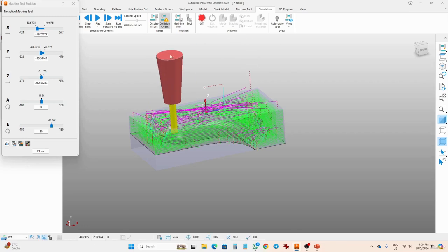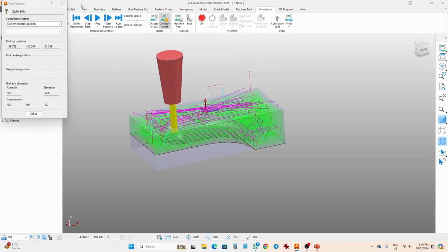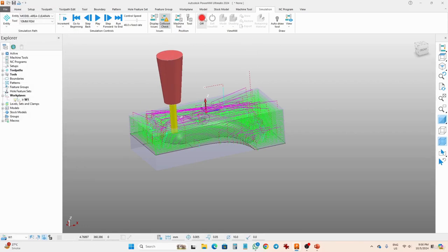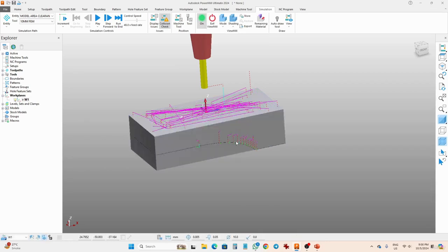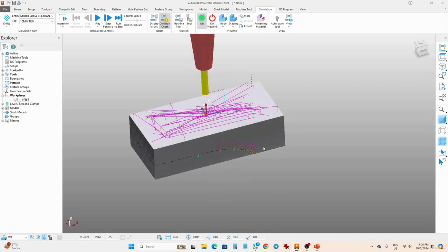And then if you want to perform the operation in ViewMill, that would convert your toolpath to a real view, showing how the material is going to be cut down. So just go to the beginning view and click on this red icon, which will show you the ViewMill position. It's going to take some time.